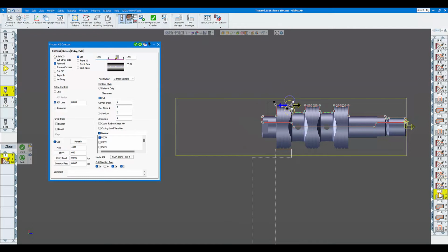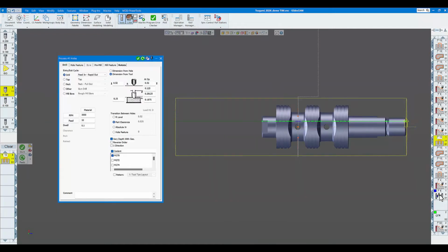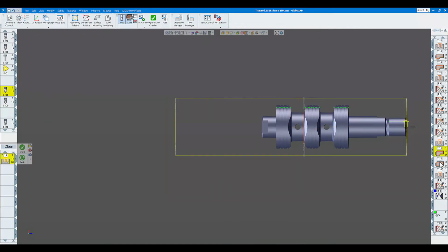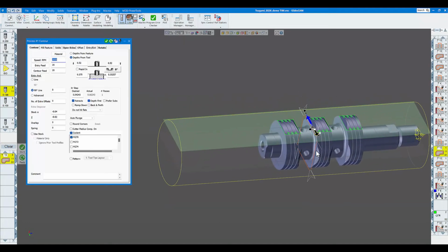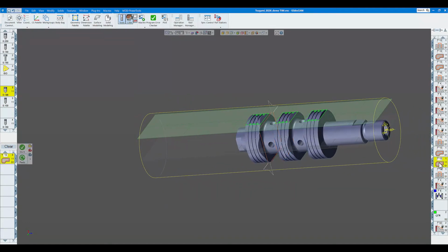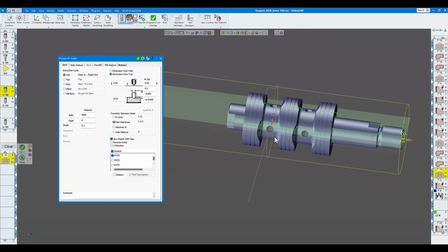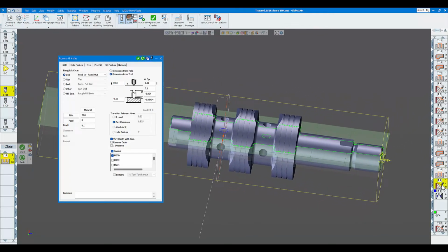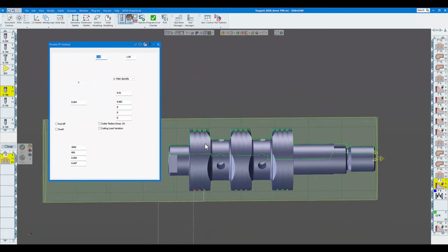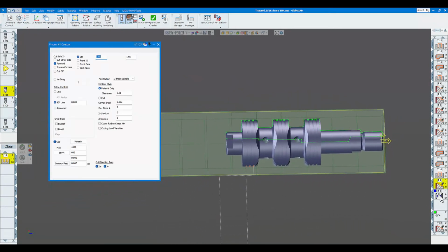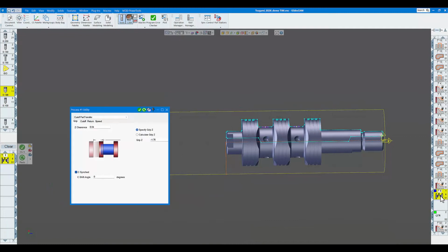And we're still drilling on here, and of course finishing these 45 degrees, that side and that side, and finish drilling the holes through here. And of course the grooving, and then the last utility operation on flow number 1 is we're going to do a cutoff part transfer.